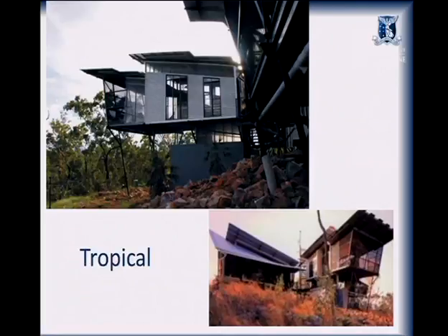That'll be nice. Okay, so we talked about having to deal with different climates, and we can, for the most part, say that a typical house has one person per 50 metres squared and appliance density of whatever, so it's not greatly different in houses. So we're really designing for the outside climate in most cases.